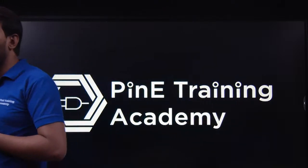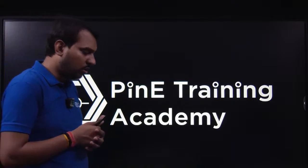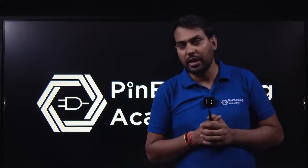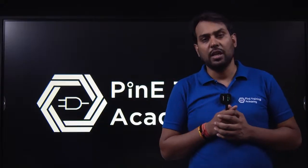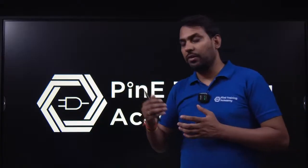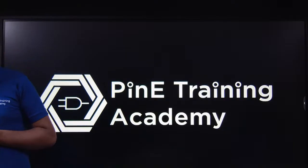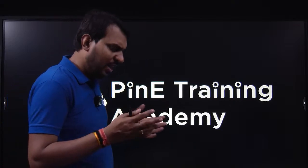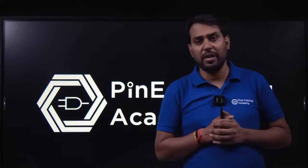If two metals are in parallel, of course it will form a capacitor. So these are the parasitics, and they will affect your result. How can it affect your circuit? We generally say you have an input with a sudden change, and the capacitor charging will take time, exponentially. The expression is v final plus v initial minus v final, e to the power minus t by tau, a very basic equation. This comes from the basic first order equation, dy by dx plus py is equal to q.